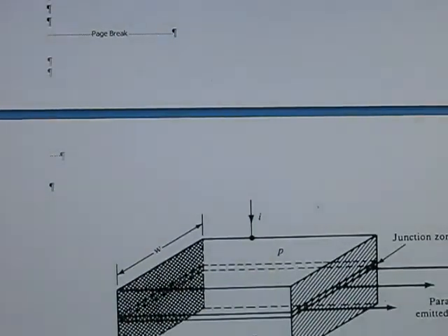So here we actually see a laser diode, N-type, P-type, and there can be other materials in between here, the junction, that help set the band gap to what we want. And in the back we have a completely reflective surface. In the front, a partially reflective surface.